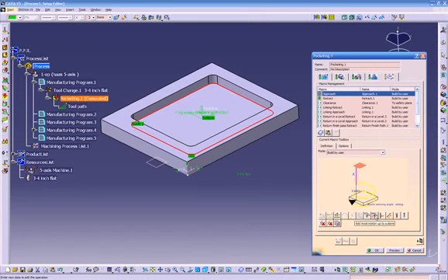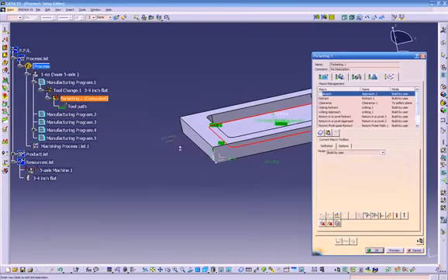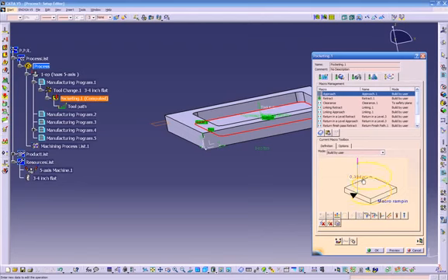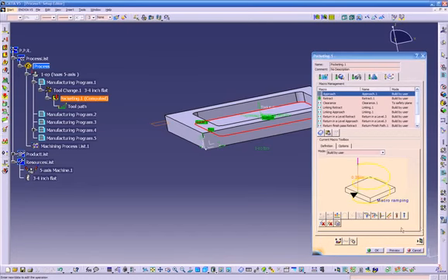So I'm just going to click on this, and automatically we get this rapid and the plane. I select my plane, and automatically the macro knows this is my plane. We also can edit this 394 ramping distance. You just double click on it, you can change it, for example, 250.